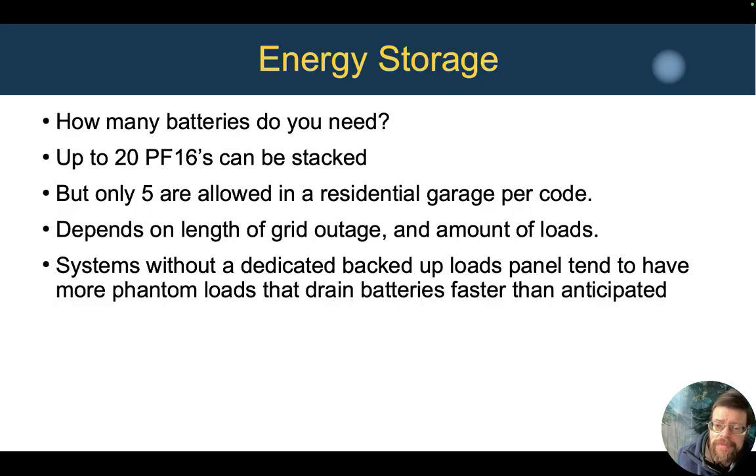Utility rooms are typically limited to 40 kilowatt hours, or 2.5 of the PowerFlow 16s. Obviously you can't do half a battery, so 2 of the PowerFlow 16s, or 8 of the PowerFlow 5s in a utility room, or 5 of the PowerFlow 16s in a garage.